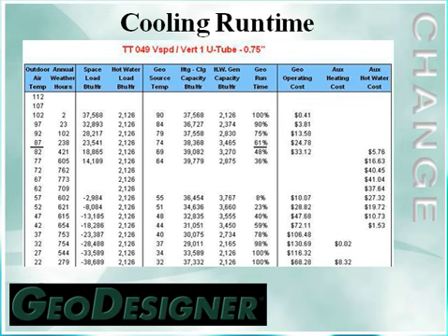We look between 82 and 87 bin hour, and we should hit about a 50% run time. If for some reason we're outside of that window, if we're still only at 30 or 40% run time by 87 bin hour, we might want to consider a smaller unit or consider using one of our dehumidification options. You do have an option to give the unit an input, and we can slow the blower down during the cooling mode on demand. Running a lower airflow through the air coil will pull more moisture out of the air.